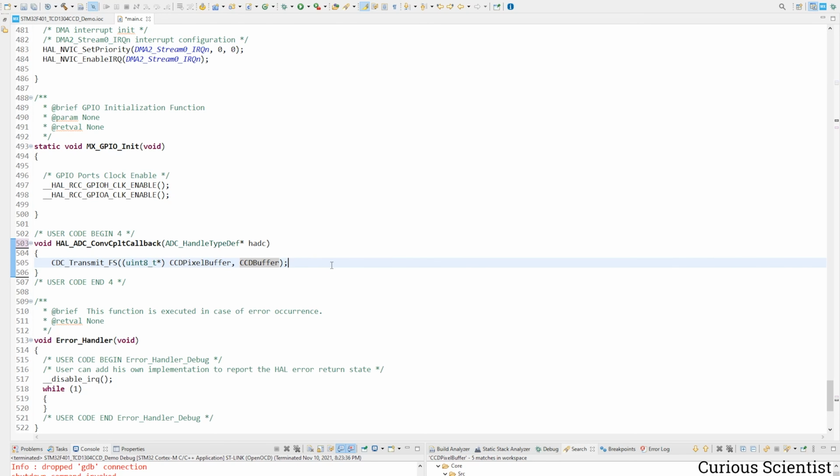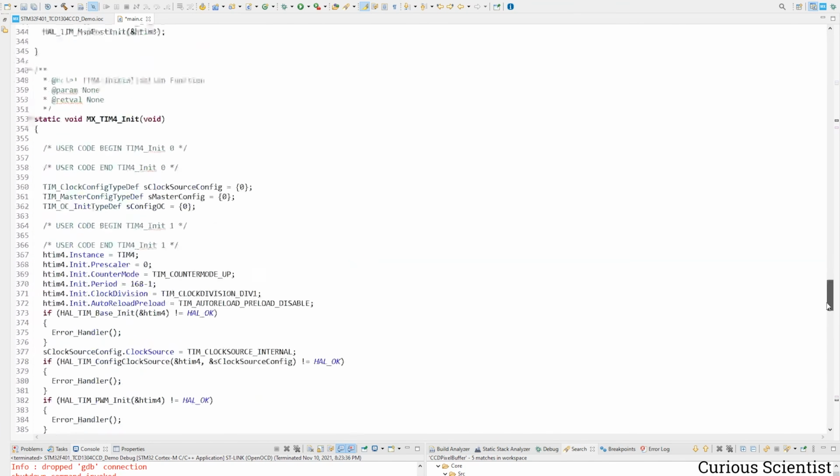So number 1 with number 2, and then number 3 with number 4, number 5 with number 6, and so on from the array. You have to combine these two 8-bit numbers into a 16-bit number, which will be finally your 16-bit integer, and that has to be converted into a normal decimal number or something that is human readable. So this is done, and now we have to start the DMA.